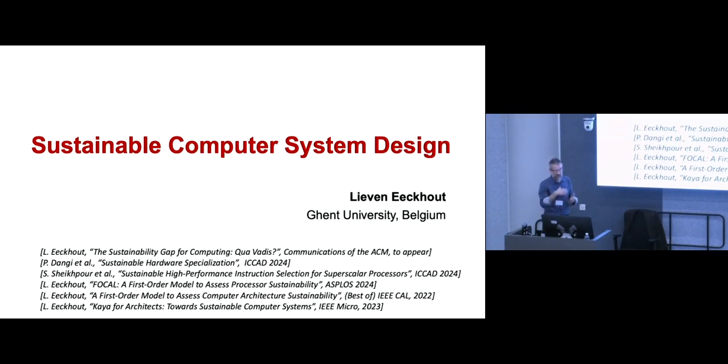Overhead of reconfiguring is one issue. At least for FPGAs, the time to reconfigure can be quite time-consuming. It's much less time-consuming in a CGRA, because you can think of it more like a reconfigurable processor architecture, in terms of how data is flowing through the different compute units. It's more programmable, I should say, compared to an FPGA.